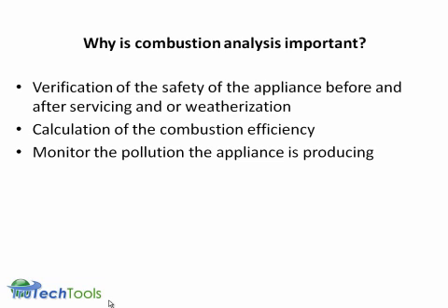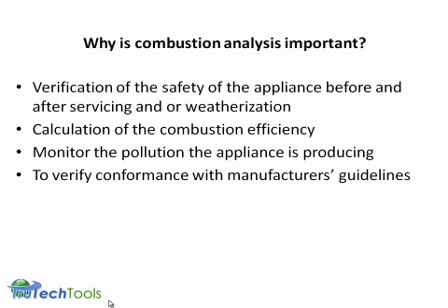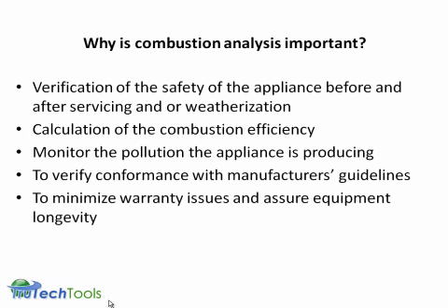We want to monitor the pollution the appliance is producing, whether that's CO or possibly NOx or SOx. Verify conformance with manufacturer's guidelines and make sure it's operating safely. And minimize warranty issues and ensure equipment longevity.